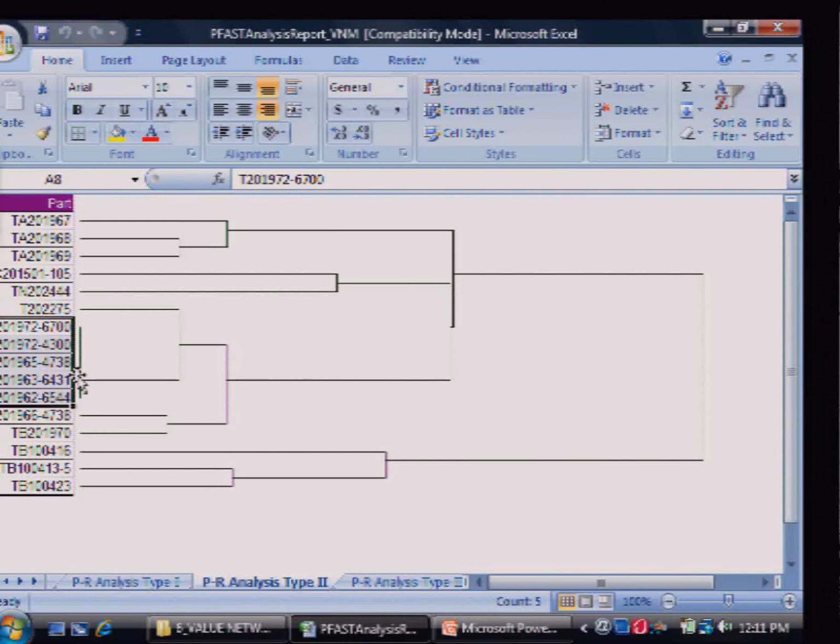Now, this family of parts differs by at most one center, and therefore if you look at this PR2, this is the slightly bigger part family. So you're saying, if I try and make a few more parts, they are not identical, their value streams could not be merged, but if I could put work centers into a flexible line, I would make that flexible line make all these components. And if I wanted to make a slightly more flexible line, then this would be my larger part family.